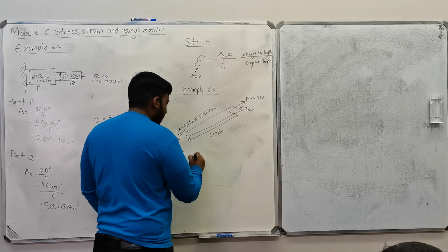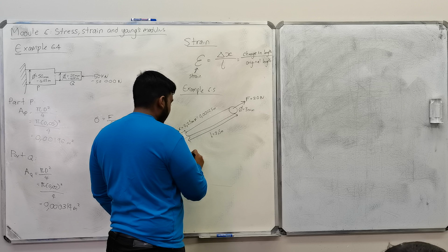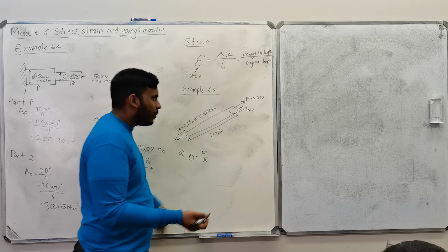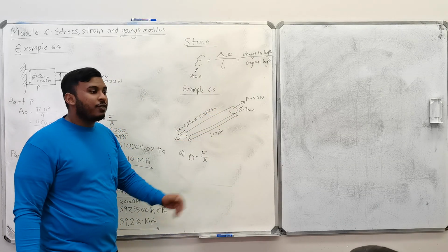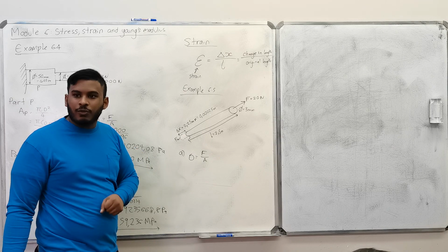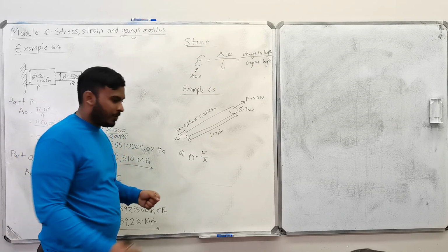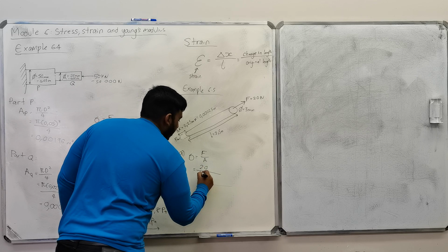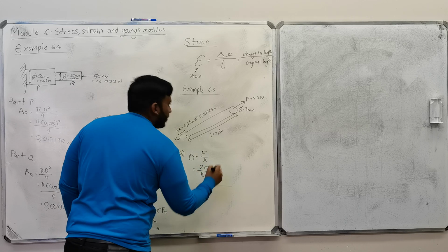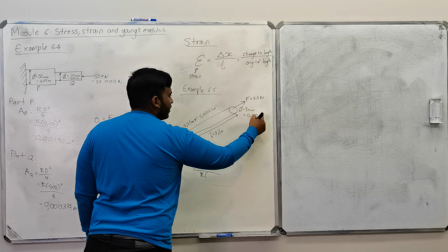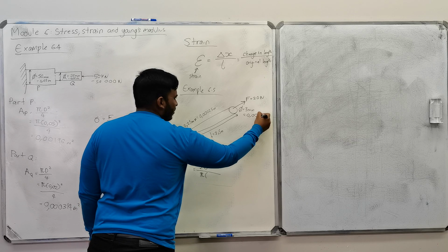Now, stress is equal to force over area. We know the force is 20 newtons. It's force over cross-sectional area, so it will be force over pi d squared over 4. Yes? Okay. So this here is actually 20 newtons all over pi times the diameter, which is what? 0.003.